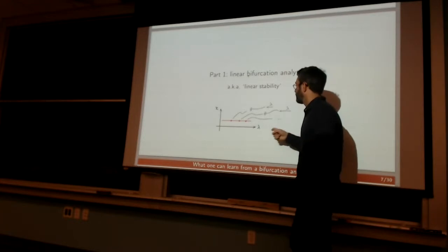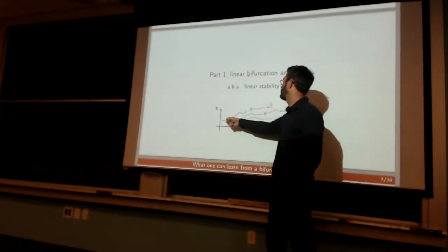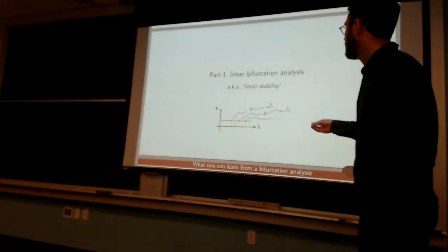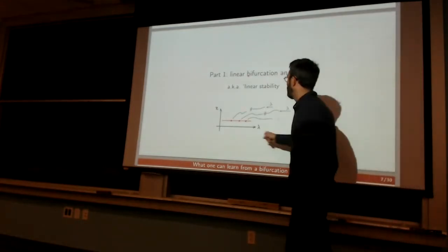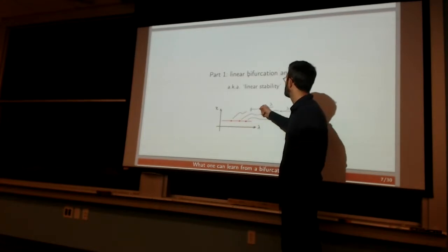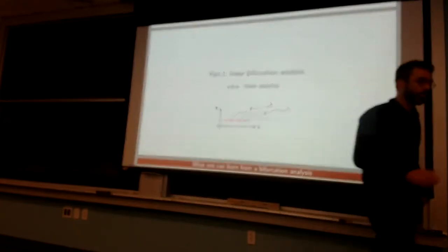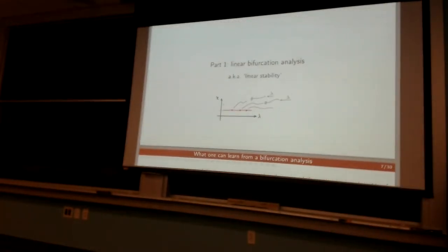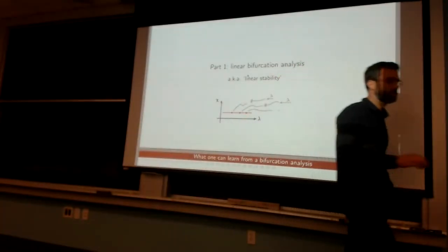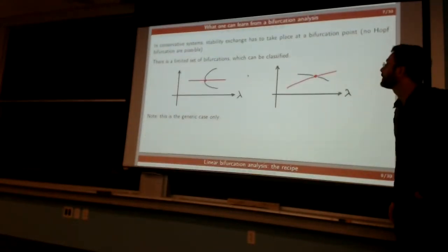And so that's really what you would do for the Euler problem, where you have a base solution. In that case, you could pick the unbuckled solution that has purely axial load. And then identify special values of the load where you have linear modes that will then give rise to the full branches, but we won't be concerned about the branches for the moment. So we call the method what that gives you the critical load and the branches. Okay, so why do we do that?